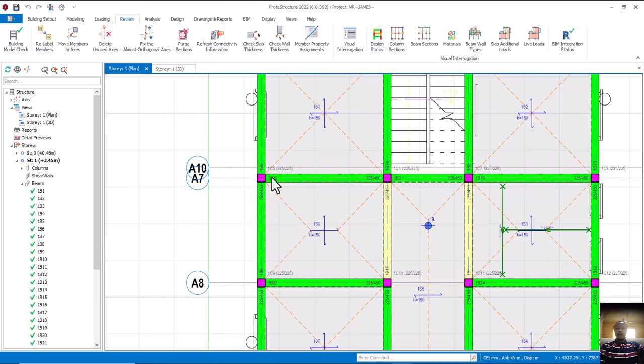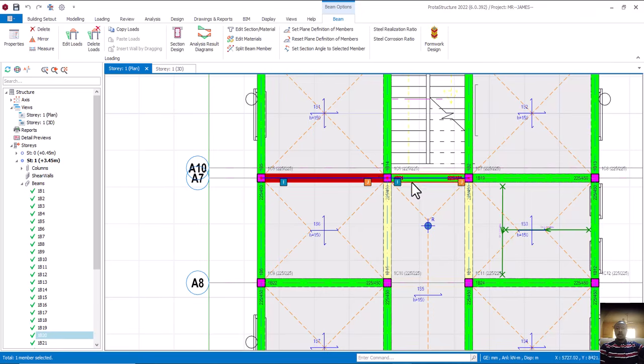Around this place. So that's why if you look at our bending moment diagram, that idea or knowledge of your bending moment diagram will also help you a lot. Can you see it now? So as it goes up like this, there's a hugging moment. So on this place, there's need for reinforcement to tackle it, to handle it. So at that point, you cannot hinge this place because there's a hugging moment around this place. Is that okay? So that is that.